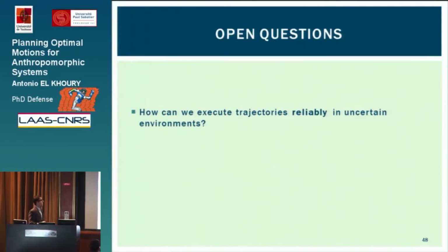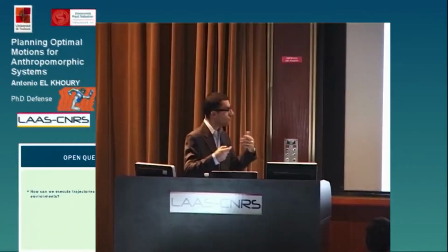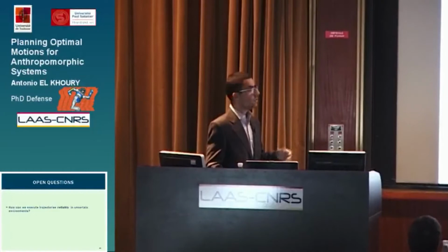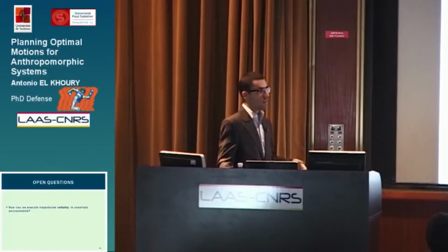And what I would like to argue here is that we could, for example, use the decoupled approach, but not only for planning. So we could, for example, use the first part of the decoupled approach to plan a draft path for a very simple system. And then once we have found this path, we could rely on the online controller to either reshape or approximate this collision-free path if we have the right properties, in order to generate a trajectory that will always be feasible on the robot, regardless of the uncertainties in, I don't know, for example, the obstacles, the contact forces, and so on.